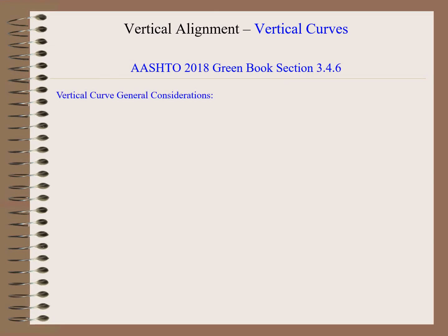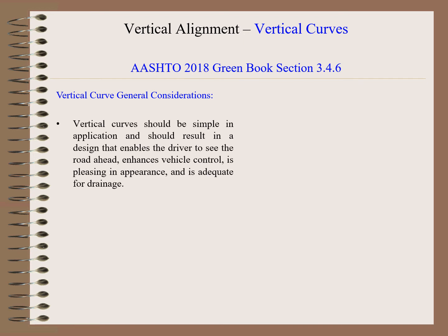Vertical curve general considerations. Vertical curves should be simple in application and should result in a design that enables the driver to see the road ahead, enhance vehicle control, is pleasing in appearance, and is adequate for drainage.